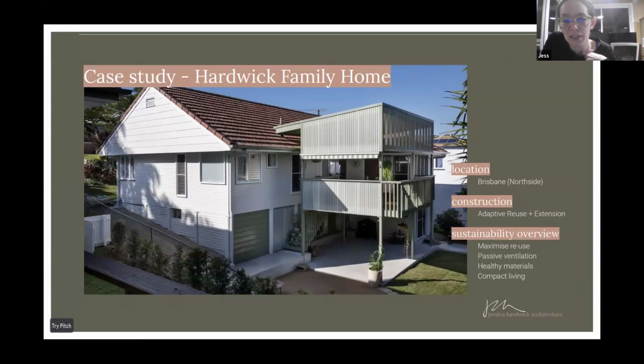We're also using Proclima building wrap to make sure that we're really nice and airtight in our facade. We're ventilating our facade, as in we're battening off. If our stud is here, we then have a batten and then the cladding applies onto that. So it's creating a really breathable facade that will never have issues with condensation buildup inside the structure.